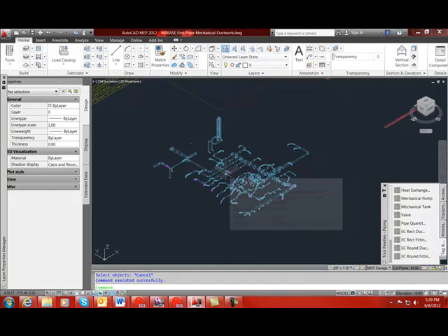Alright, now that the ductwork is broken, we're going to use the Duct Schedule Data command to ensure that all of your duct and fittings have the appropriate data assigned to them. So we're going to go up here to the drop down, Duct Schedule Data. We're going to attach it by clicking Enter. We're going to type in all to select all of the duct objects, and we're going to click Enter one more time.